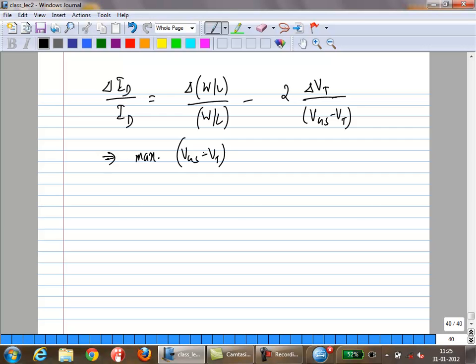Okay, so you wanted to minimize VGS minus VT for the differential pair and maximize VGS minus VT for the current source, right? For noise. Turns out, for mismatch, it is very similar. The behavior with VGS minus VT is very similar. That's the idea.